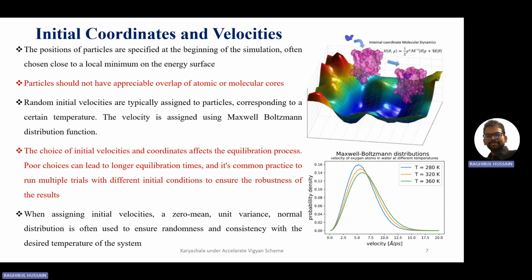Once they repel each other, so much energy will be created that your simulation will fail, because the thermostat is not capable of absorbing the additional energy. So you need to put some minimum allowable distance. Generally 2-3 angstroms is okay.